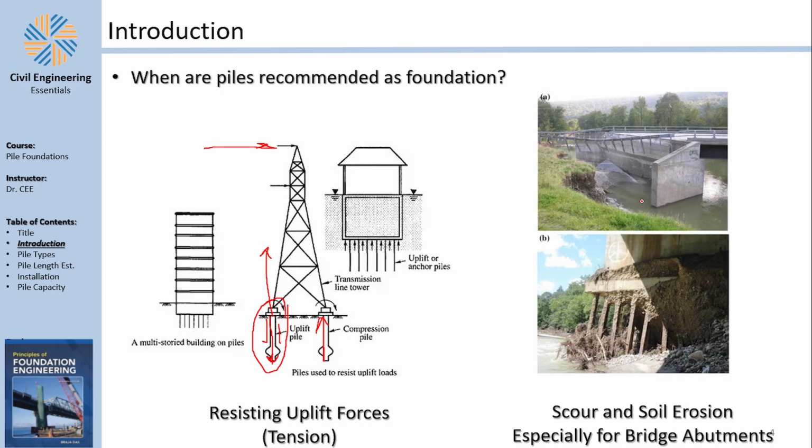If you have scour or earth erosion, you might need piles, because scour and earth erosion would erode the soil below your ground. Of course, this is an extreme case here. It should never have reached this position. But I'm saying even if you have some slight erosion here, you don't care because your pile is embedded in the strong ground. Of course, here you should care because the scour is way more than you can safely consider. But I'm just showing you here an extreme case. So that is when we use pile foundation.